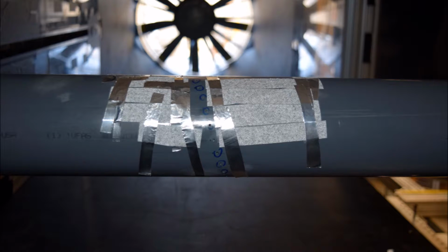After the first run of measurements and observations, the wind tunnel was turned off completely so the cylinder could be modified. It was decided to trip the flow by attaching several strips of sandpaper approximately 6 inches long to the front half of the cylinder using aluminum tape. 6 strips were used to cover as much area as possible on the upper front half of the cylinder. After ensuring the sandpaper was as secure as possible, the wind tunnel was secured, the safety working procedure was followed, and the exact same process was repeated as before, with both visual observations and pressure measurements being taken at the same air velocities in the same order.